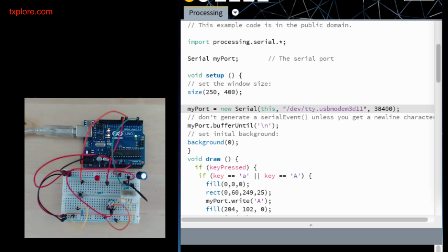An easy way to get data from the Arduino to the processing sketch is to just put it in a comma delimited string. So what I'd like to be able to do is to have value A followed by value B followed by value C with a comma, and then with a println I'm going to insert a new line. So the processing sketch is going to capture this text, right?